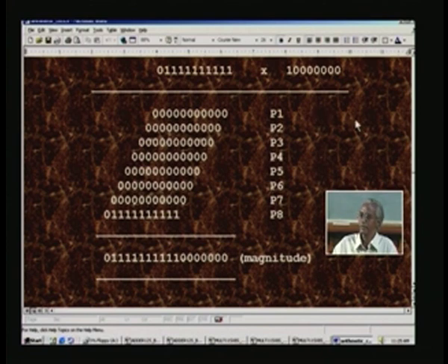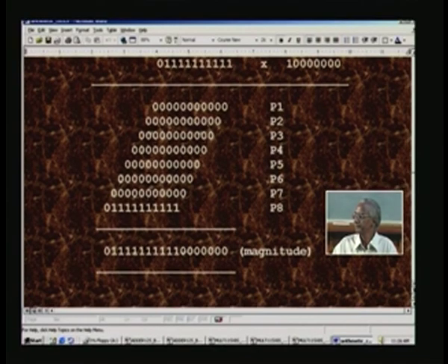Once again we have the second stage of addition and add 2 numbers at a time, and out comes one result, and there will be 2 such outputs, and those 2 we will add in the third stage resulting in one final sum, and all this would be registered at different points of time. In total we have 8 clocks, and therefore 8 pipeline stages inside, and hence 8 pipeline registers as well,